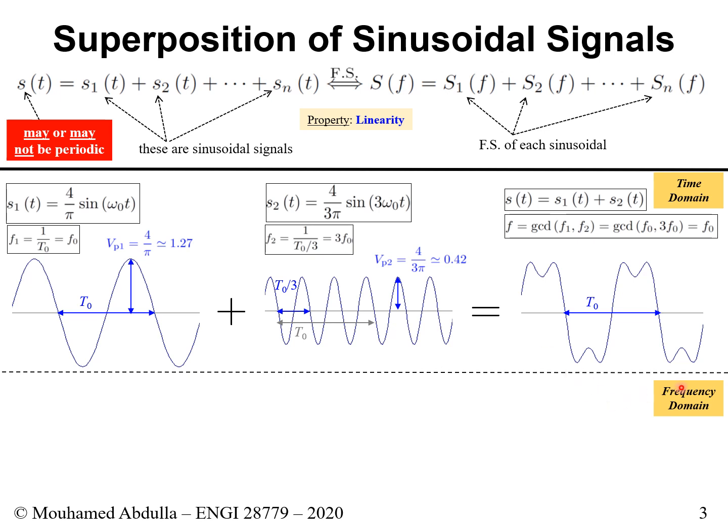Okay, so let's look at the frequency domain representation of these signals. Let's look at this one here. Remember we did this in lecture 3: the frequency domain of a sinusoidal will simply be a spike at this frequency, f naught. The value of the spike is the value of this 4 over pi, and 4 over pi is 1.27 volts.